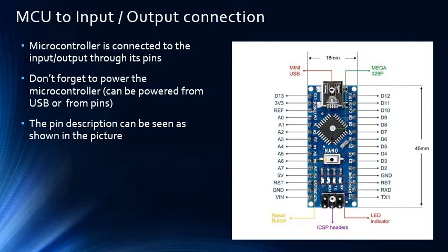And this 5 volt is the output voltage, not input voltage. This 3.3 volt is also output voltage. That means if you already provide some voltage here, then there will be 5 volts output here or 3.3 volts here. The purpose of this voltage is to power other devices, but you need to remember the current is very limited.